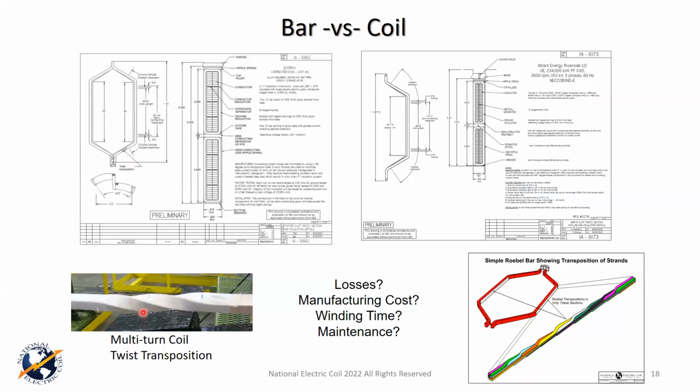And that twist kind of looks like this. And what that is depicting on the drawing is what you see right here. Okay, and it is a type of coil transposition to help equalize the slot voltages and make the thing a lot more efficient. All right, and it's kind of a trick in itself because you have to do this without shorting any of the strands or compromising the turn insulations on the surface. So it's an interesting manufacturing challenge.